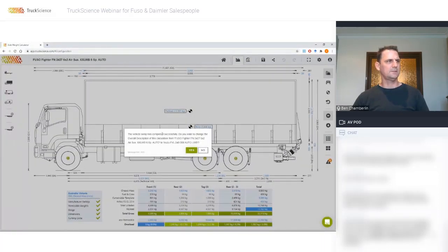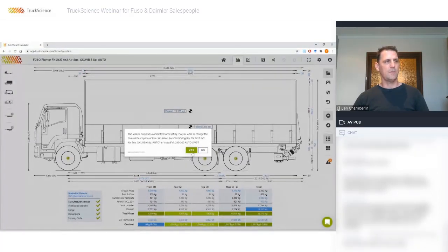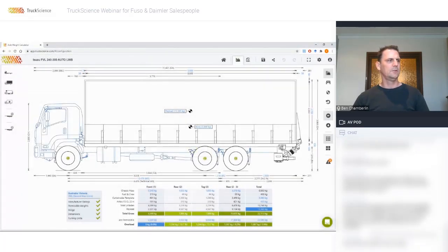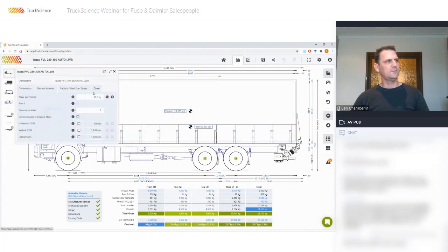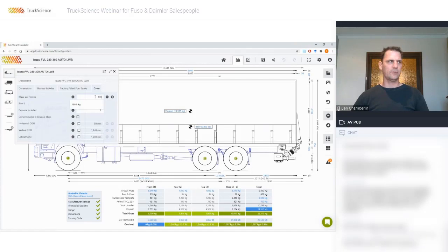It's going to ask us, do we want to rename that as the Isuzu? Yep, because it's no longer the FUSO. And although they have 6.5 tonne on that front axle, they've actually dropped back by close to 0.5 tonne on that overall payload. So it's an interesting perspective. Now, when I change that, we have to add in the 100 kilo driver that we had on our truck as well, and then make it apples for apples.